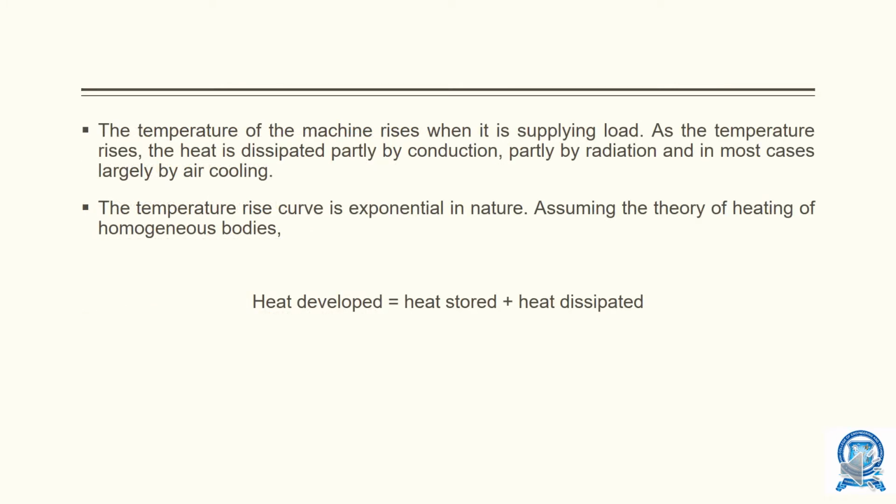The temperature of the machine rises when it is supplying a load. As the temperature rises, the heat is dissipated partly by conduction, partly by radiation, and in most cases largely by air cooling. So the temperature rise curve is exponential in nature. Assuming the theory of heating of homogeneous bodies, heat developed is equal to heat stored plus heat dissipated.